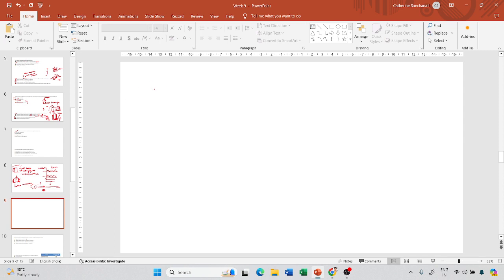I need the response of the material at different temperatures and different frequencies, right? So I will take a sample and condition it so that it is brought to the required temperature. I will put it in an environmental conditioning chamber, and first identify how much time is required for the sample to reach that temperature by using a dummy sample.